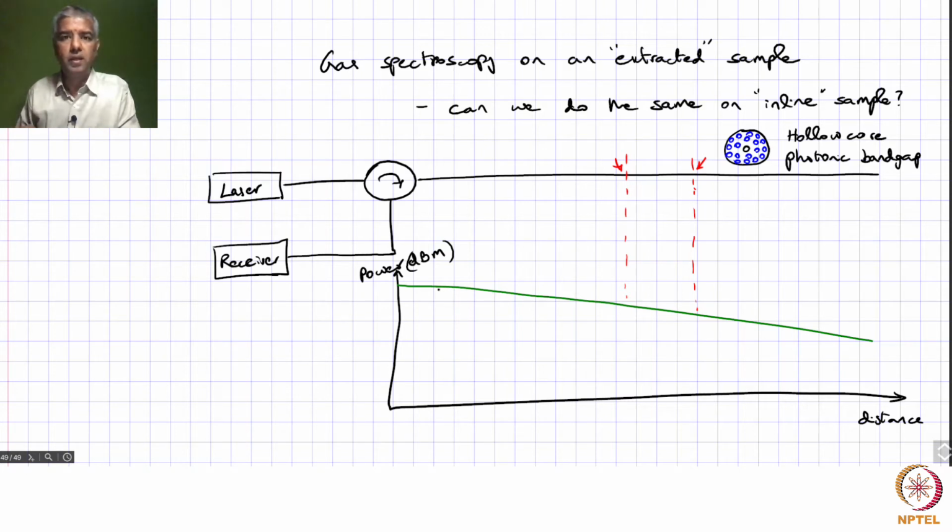What we saw was it corresponds to 1.1 micron, right. At the resonant wavelength, you will probably have something that looks like this. Up to this point, the background losses will be the same, but at this point it will take a different slope, because of the extra absorption happening within this region, and then it will go parallel with the other line. Based on that, you can figure out the concentration of nitric oxide within that particular region.